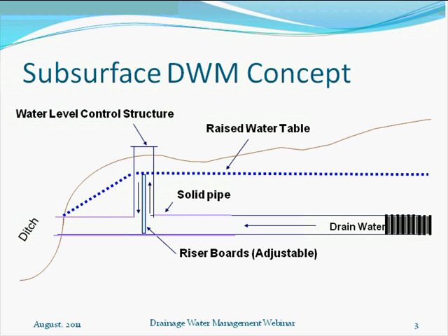I wanted to note for you again, although we've mentioned it before in this presentation, that the work we're doing on these tile drainage systems is really just a way to control the outlet of the drainage system and reduce the flow of drainage in selected parts of the crop year. So we're not intending to go out and increase any amount of drainage out in the field. We're not proposing to add any kind of surface inlets or underground outlets into the system. We're just proposing to take a look at what's happening right there at the outlet of the tile before that water gets a chance to go into the surface water.